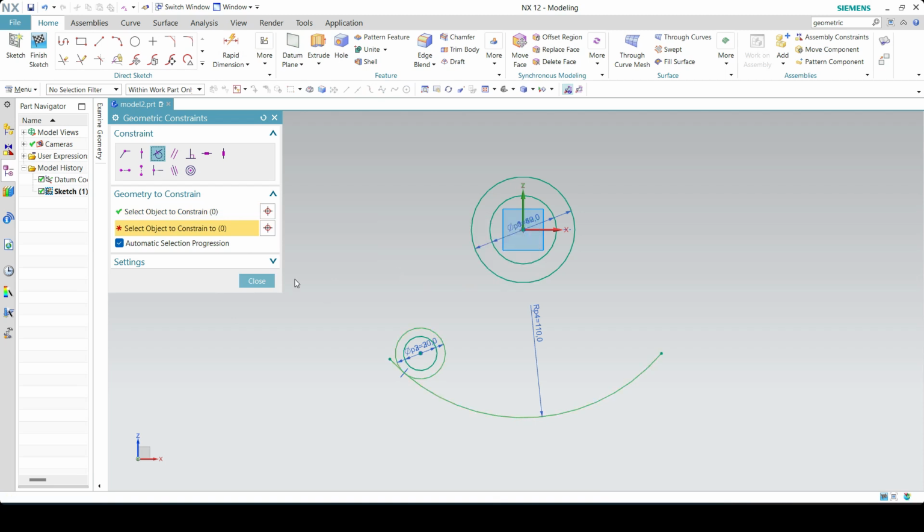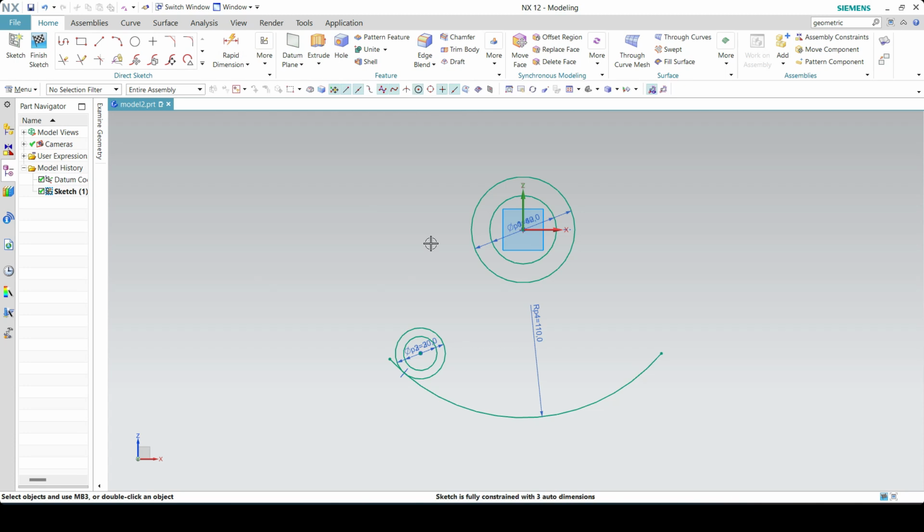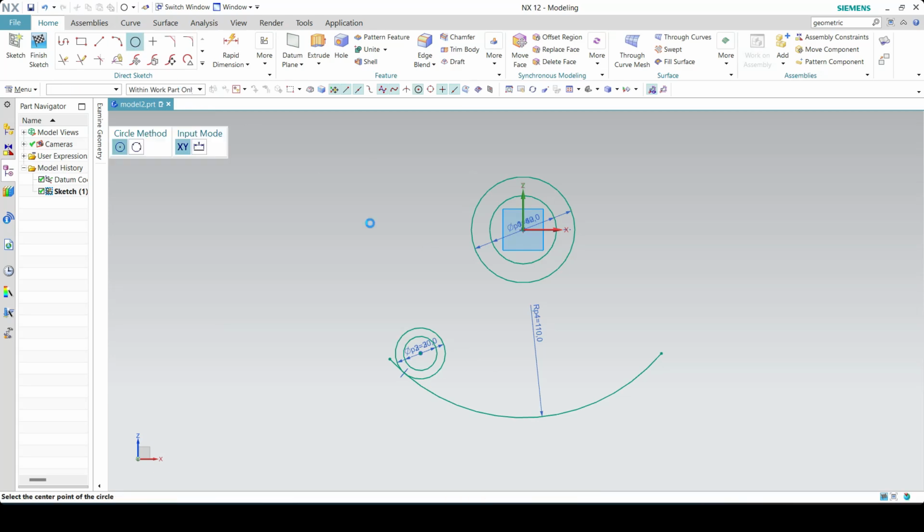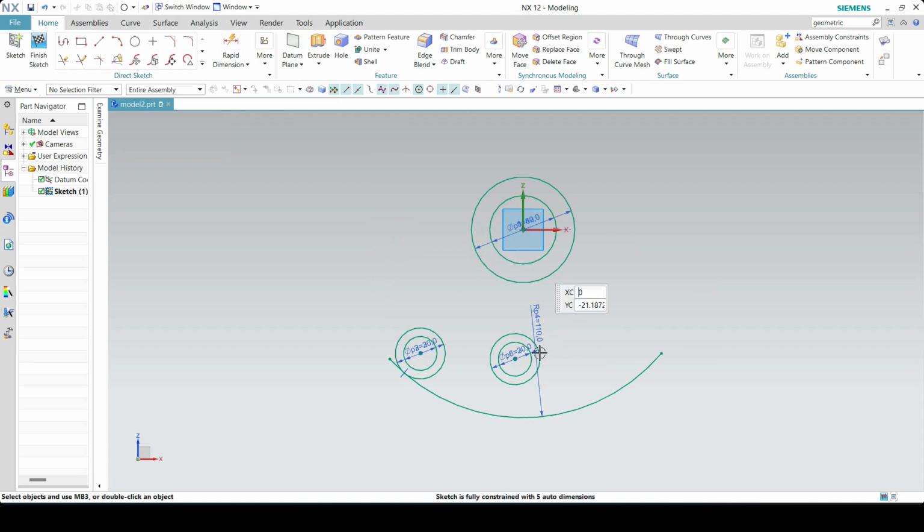The constraint already exists. Okay. After this, we'll create one more circle here, in the middle, with the same dimensions, dia 30 and dia 20. So we'll again click on the circle command, and here I'll create two circles of dia 30 and dia 20. Select this. Now I want to match this circle, press escape. Now I want to match this point onto the center line.